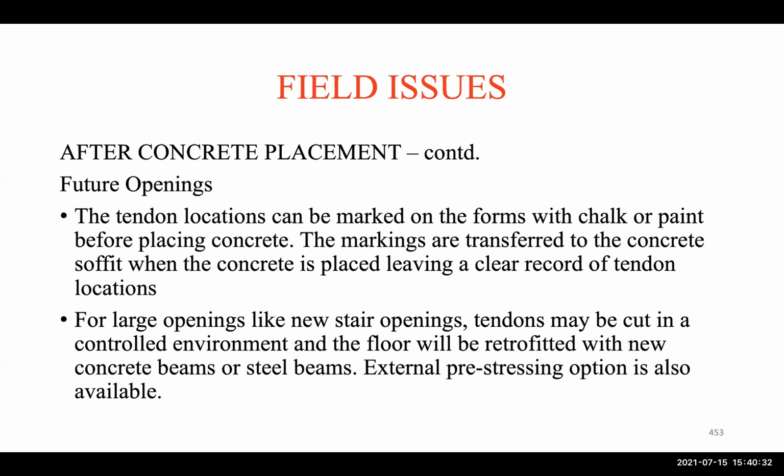Okay, so we have to be careful about openings in the floors and doing repairs. We have to know where we can have openings. If there's a future opening planned by the architect, then of course the engineer will design based on that. He or she will design the tendons to go around that area, and that area will be just reinforced concrete.